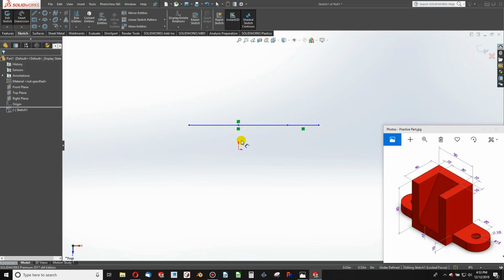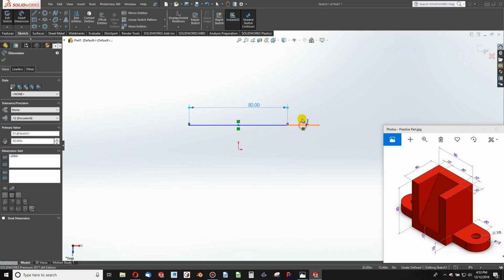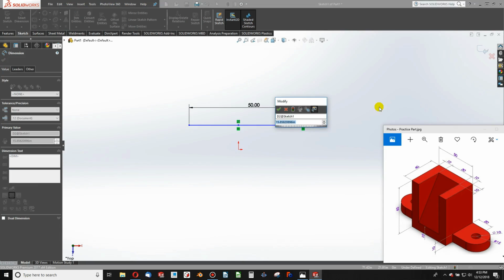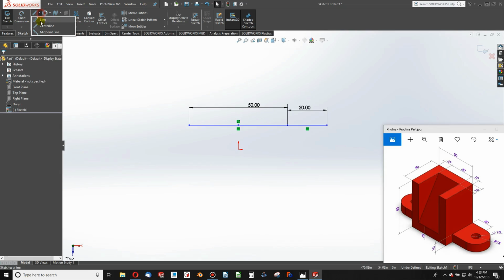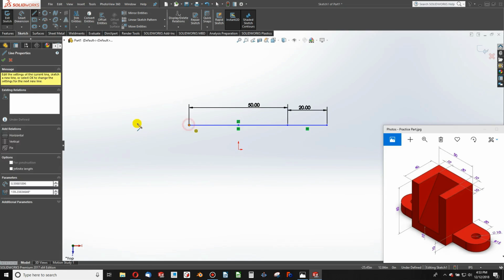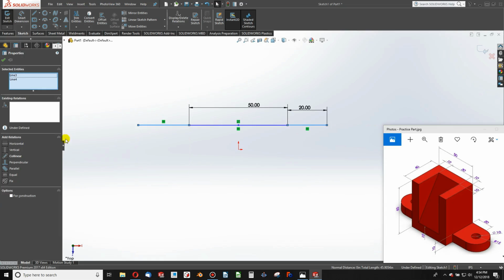Okay, so I'll add some dimensions. 50. I'm sure this isn't millimeters, but I'm going to just keep my default units for ease of editing later. So this will just be 25.4 times larger since I'm in inches, but the dimensions are relatively arbitrary for this exercise. I can add in my other line because the other side, as would be implied geometry, is the same. So I'll add in equals over here.